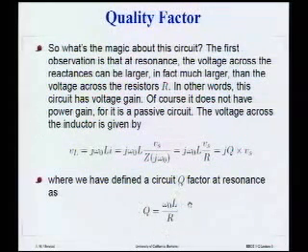Now what's interesting about the circuit is that omega naught, L, and R are things that we really have control over. So let's say I want to obtain resonance at, let's arbitrarily say, 1 radian per second. If I make omega naught L larger than R, then the Q of this circuit is greater than 1.